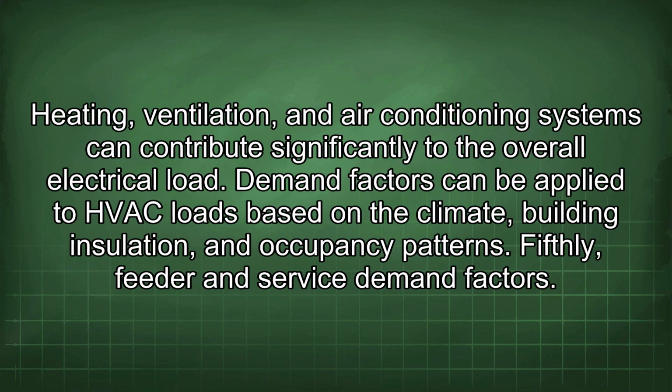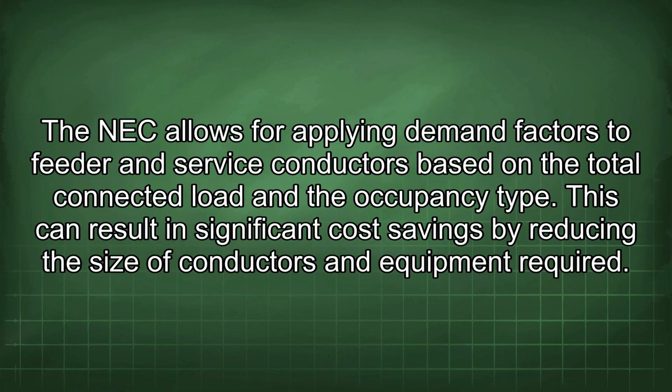Heating, ventilation, and air conditioning systems can contribute significantly to the overall electrical load. Demand factors can be applied to HVAC loads based on the climate, building insulation, and occupancy patterns. Fifthly, feeder and service demand factors. The NEC allows for applying demand factors to feeder and service conductors based on the total connected load and the occupancy type. This can result in significant cost savings by reducing the size of conductors and equipment required.